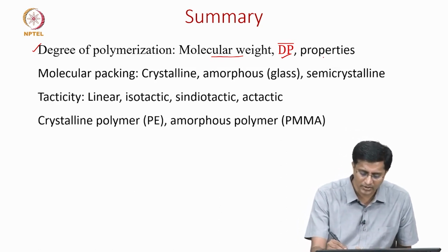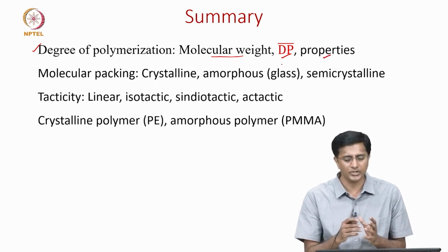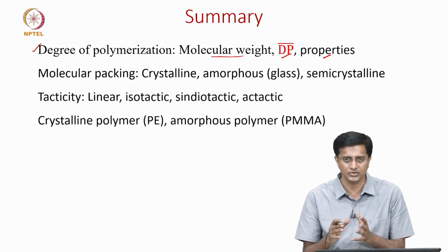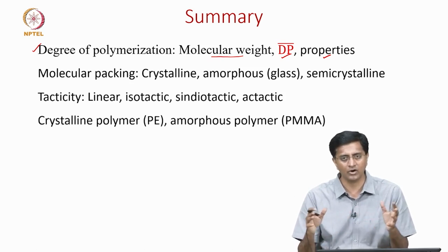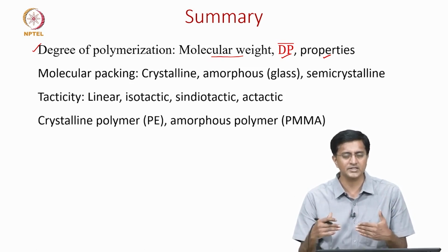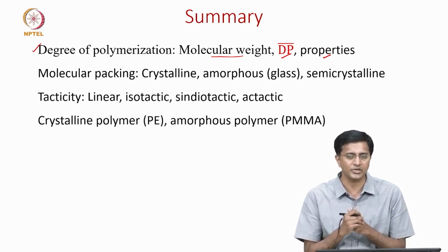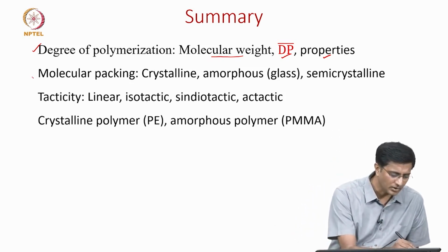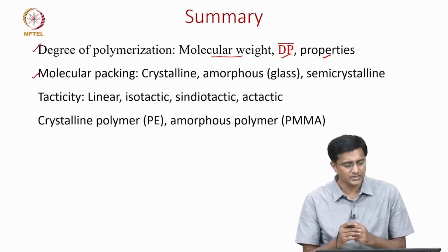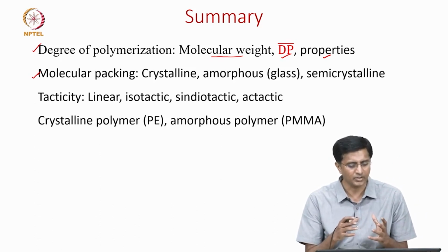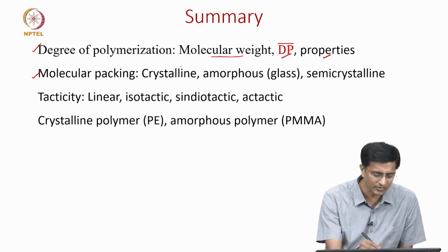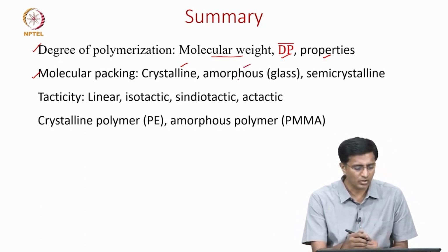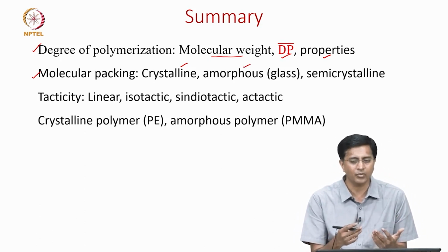We also showed that this degree of polymerization plays a big role in defining the properties of these polymers. If the polymer chains are long, usually the strength is high, the viscosity is high, and the softening temperatures are high. We also looked into molecular packing, saying that polymers can go to a crystalline form or an amorphous form, but usually there is no perfectly crystalline polymer.